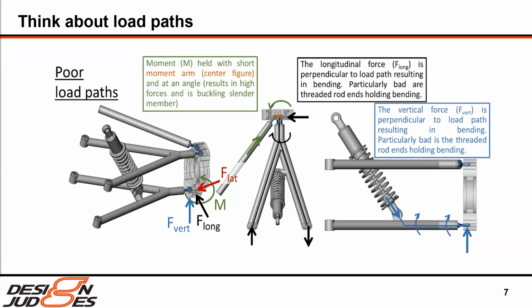They have a small minor diameter. They have some stress concentrations there, and so this cyclic loading can really easily break this off. And I've had that happen to many of my teams before.